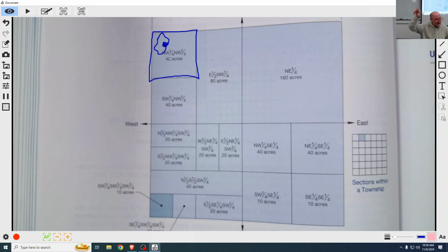I think we're in township 29 and range like 13 west of the New Mexico principal meridian, all in the county of San Juan, right? So that's how you would say where that is. That's how you locate it. That's its legal description. Fun, great fun.